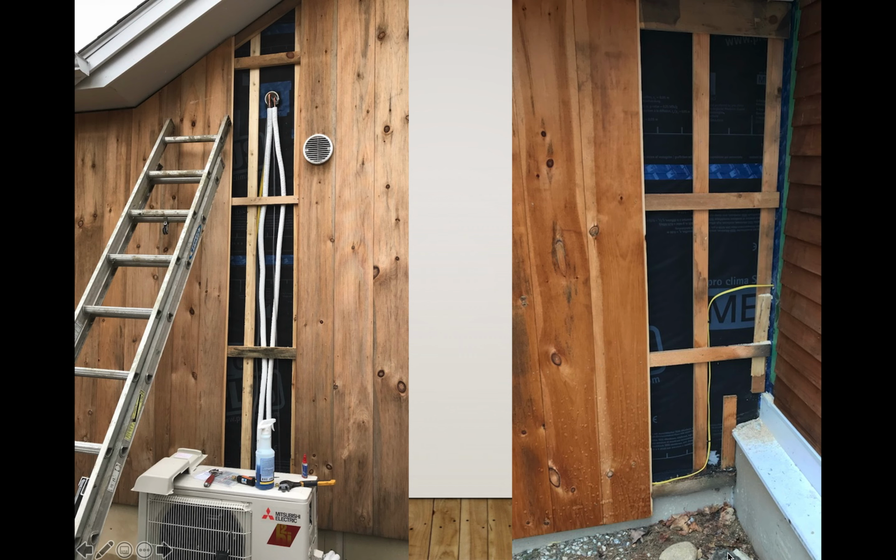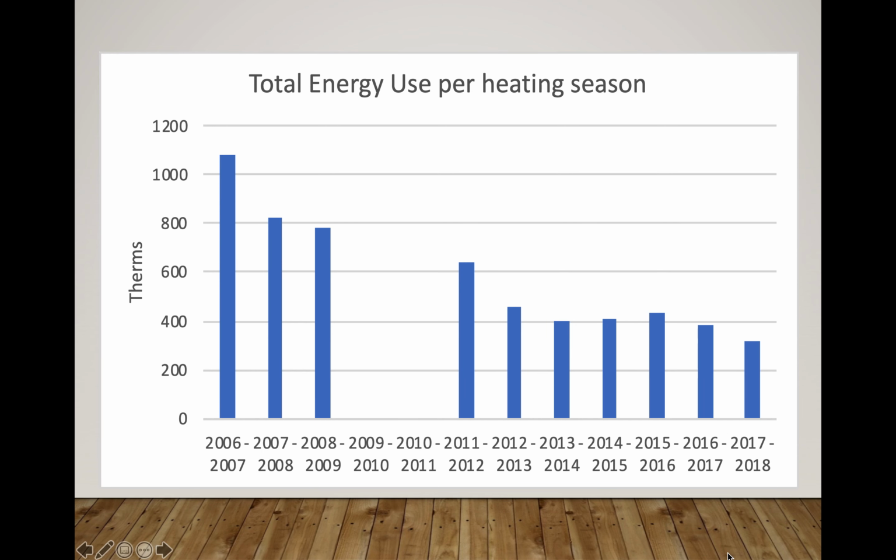So one benefit of an exterior strapped rain screen or interior strapping, especially on super thick walls, is that you can have the trades operating in any order that you want. And in this case, a few years after installing this siding, I opened up a few pieces of siding, and I had pre-placed the penetrations that I needed to get the electricity and the refrigerant line sets through the wall without disturbing the air barrier that I had built earlier.